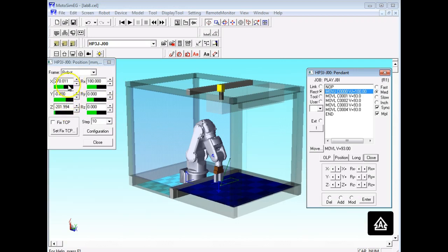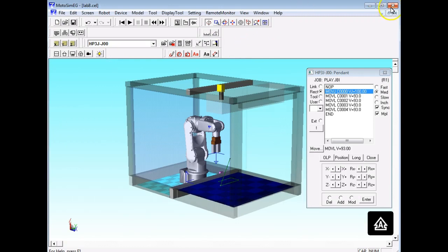So this is that Cartesian system that we were looking at. Now if I jog it in Cartesian, it's very similar to a rectangular robot. But it's real easy to jog in Cartesian, because I'm only concerned with a direction. So we can jog it here too, by the way, which we can't do with a real robot over there. So the simulation is going to give you a lot more tools to make it easier to program and get positions and stuff like that, which is really neat. If you're going to take that class, I think it's neat. You might not think it's neat.